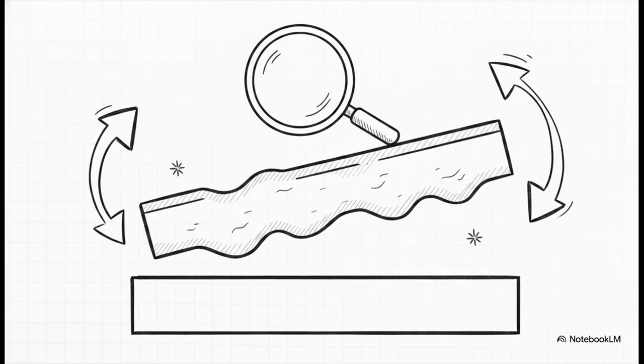So, here's the real kicker. Just because you slap a datum label on a drawing feature does not magically make it flat or perfectly round. Because datum features are real, physical, and imperfect, the ASME standard explicitly states they must be controlled themselves. Think about it. If you're going to anchor your entire measurement system to a surface, that surface needs a control, like a flatness tolerance or a tightly controlled size dimension, so that it actually sits on the datum feature simulator reliably without just rocking wildly back and forth.